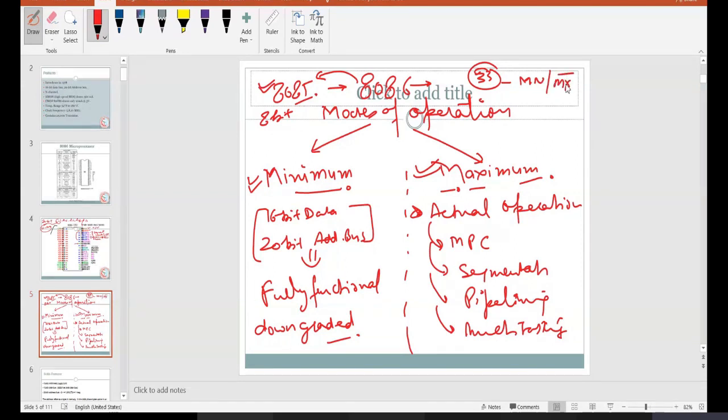So MX bar, what kind of signal is this? A signal with a bar on the top. What do we call this type of signal? Anyone, please? We have just discussed it in the previous classes. Active low or active high? Active low. Good. The signal with the bar on top is called active low. And when will it be active? When 0 is provided to it as input.